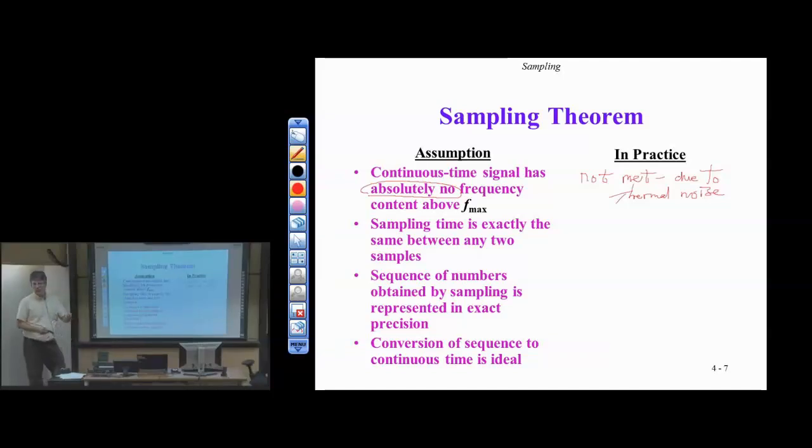That's our stopband attenuation. It's a type of filter design we choose. So in practice, we design the anti-aliasing filter. We design a low-pass filter to reduce content above f max.